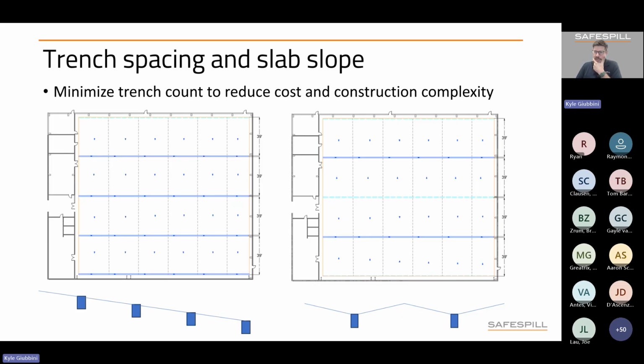Are you able to provide any guidance for space planning for ancillary equipment associated with the ILDFA pumps, flush system for a room? Any need for proximity to the floor slab? So this would involve, let's say, water tie-in or a booster pump. Typically, we'll locate that in an equipment room that's nearby. I can follow up, Carrie, and send you specific specs, but it's typically a 3 to 4 inch pump, maybe a 25 horsepower motor. So not a huge amount of space is needed for that booster pump.